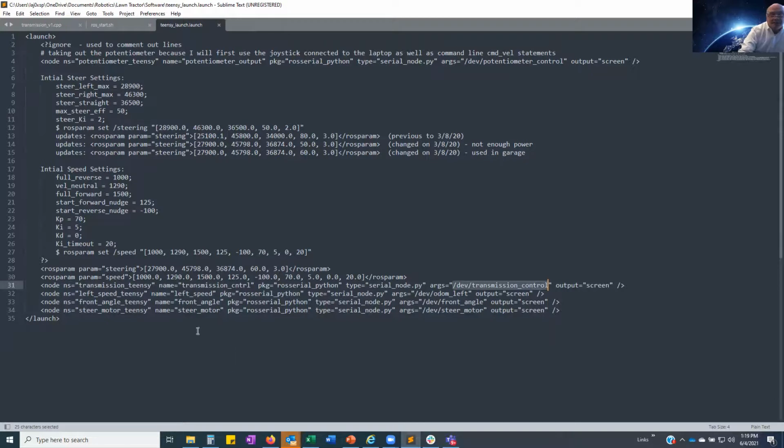And quite honestly, with Teensys, that's a really tricky little thing because I crashed a number of Teensys with that whole process. Why do you crash them? Well, because there are some peculiarities with Teensys that in the UDEV rule, it wouldn't recognize the serial number.